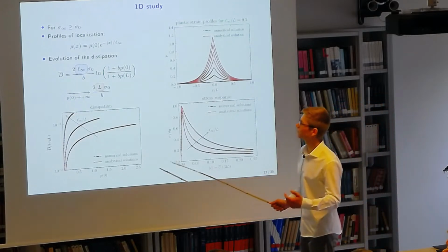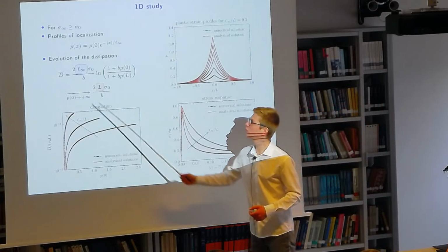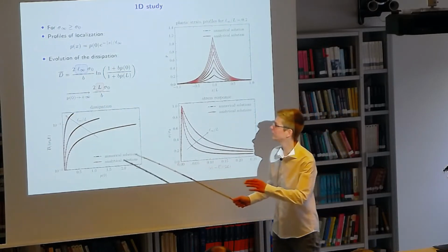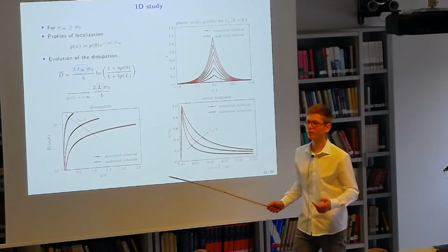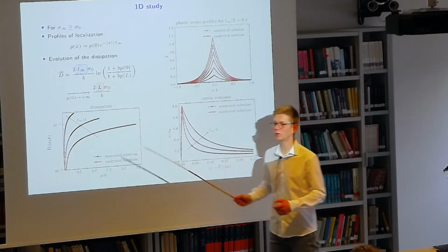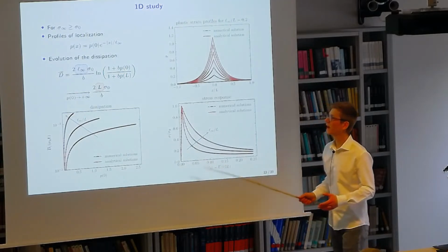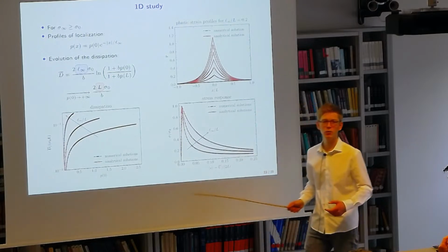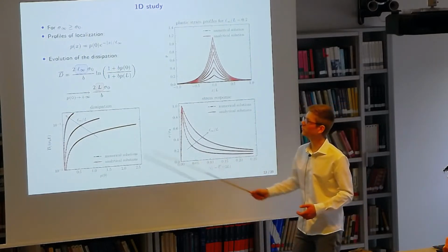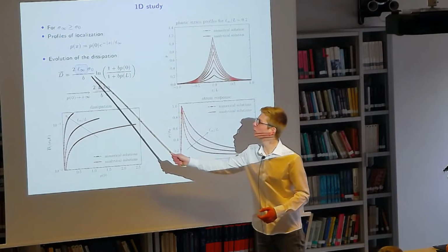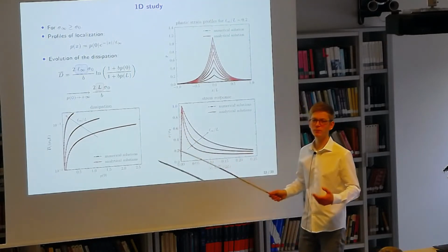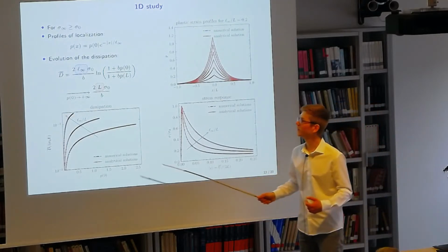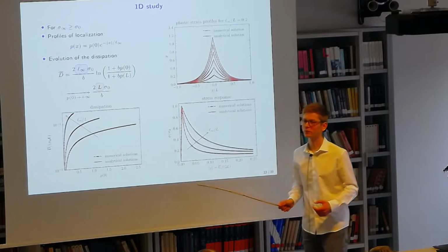Third, the property we observed when looking at the evolution of the dissipative energy was the following. For a fixed level of the displacement applied, we observed that the dissipation is dependent on L infinity, which was involved. However, when we go to the limit and the plastic strain or the loading goes to infinity, we observed that the final dissipation is no more dependent on L infinity, but reaches the same value as the ultimate dissipation of the homogeneous response, so that it is proportional to the bar itself.